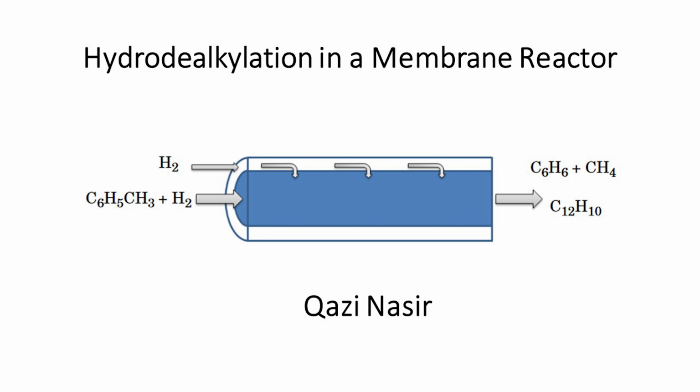Also, in this lecture, we will modify the predefined plug flow reactor in the reaction engineering interface to set up a membrane reactor model. We will also learn how to create a thermodynamic system from thermodynamics to get different thermodynamic and physical property functions for each compound and their mixture. After coupling all chemical species in the reaction engineering interface to the corresponding species in the thermodynamic system, the required species and mixture properties are automatically created and added to the property package.